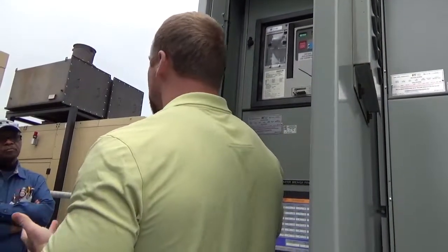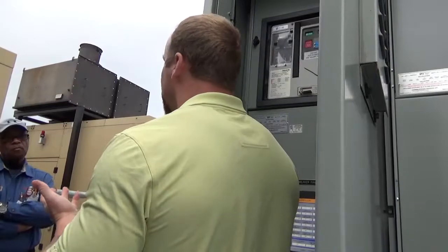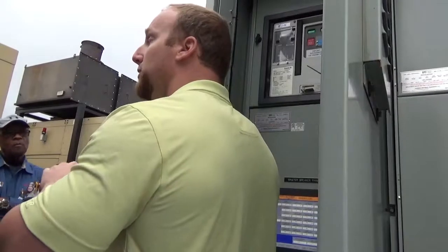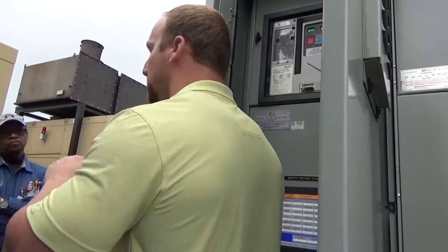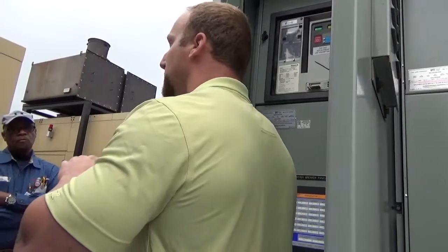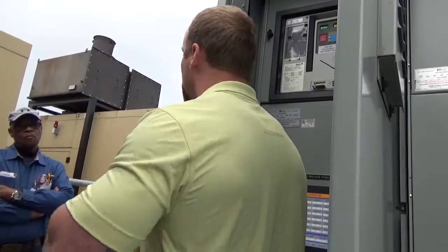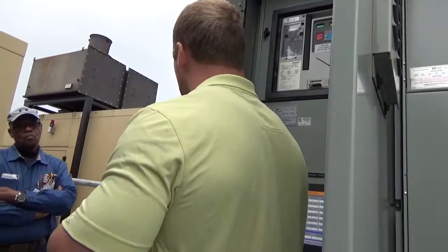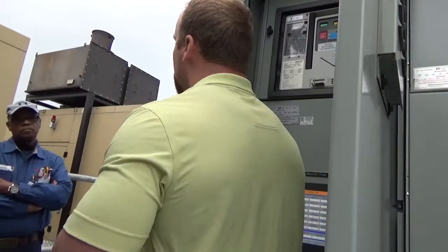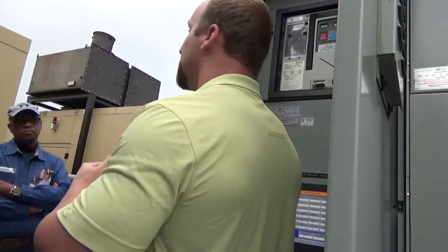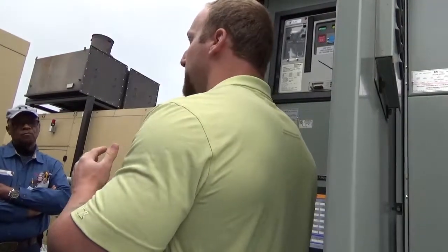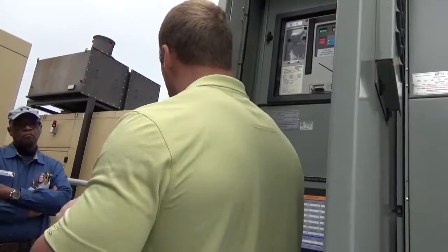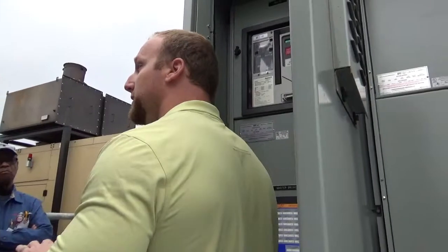If ever you guys do have site load that exceeds the percentage that it needs to add a generator, which it always is a percentage. It's not going to be at 100% of the gen load. It'll be at 70, or well, we can look, but normally it's about 70 or 80% of what the rated KW on the bus is. So if you only have one gen on the bus, you only have 1 meg on the bus at that time. So whatever the percentage is of the rated KW on the bus. Then it senses and sees, okay, my site load is exceeding what I need for that rated percentage. I'm going to go ahead and start another generator, and it will start that second gen back up and run. It'll close it to the bus and run both gens on the bus at that time.